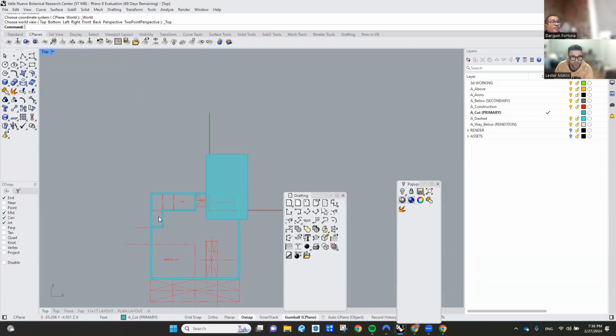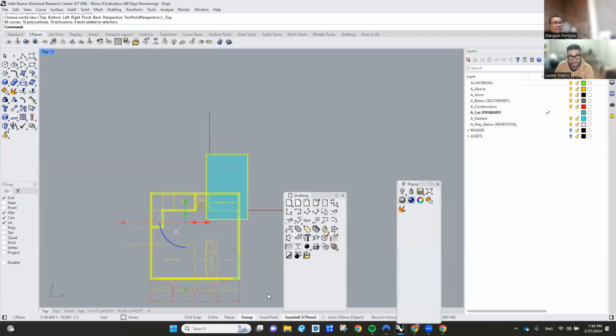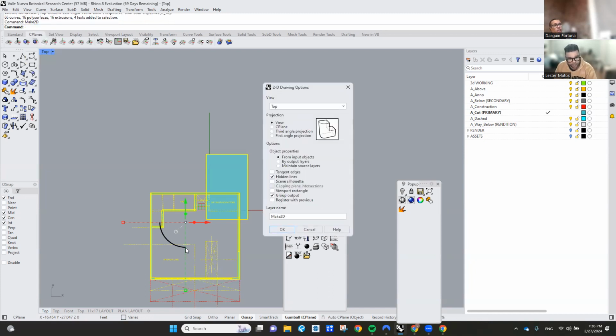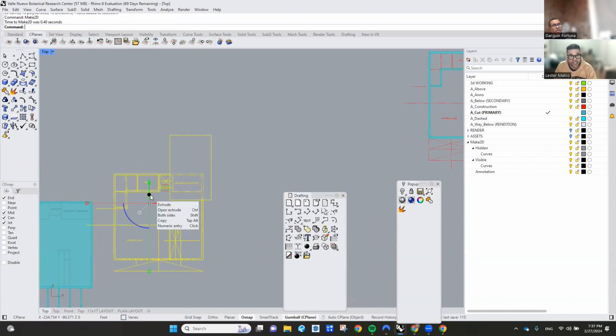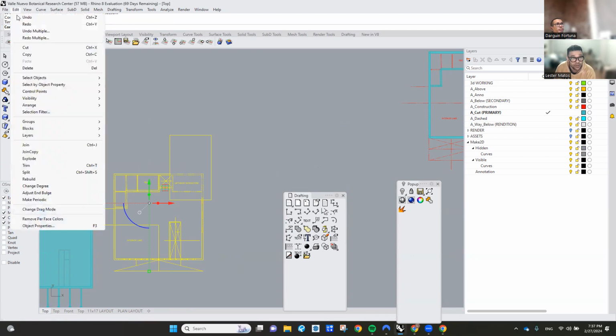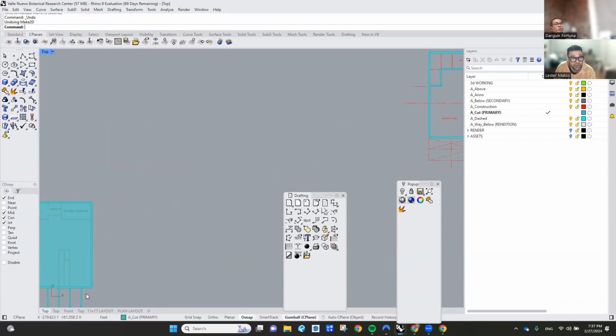Now, oftentimes I don't just use things from Rhino to create my floor plans. I actually select 3D elements in Rhino and I create something called Make 2D. It allows you to literally make a line version somewhere of that 3D element in 2D. That's exactly what I want. So I'm going to do that again for demonstration purposes real quick, undo. This is applicable with everything.